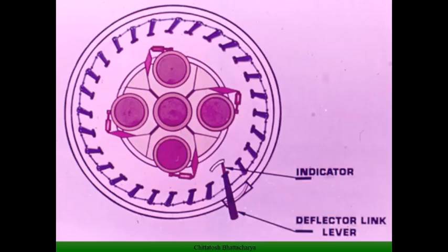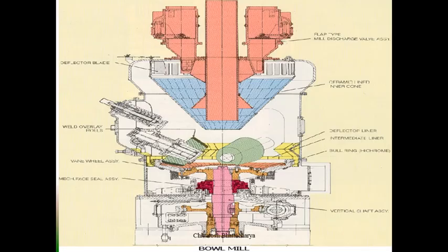Now there are venturi vanes and collars, so that speed can be maintained through the coal carrier pipes, and we also try to have equal velocity distribution across the various elevations, so these venturi orifices are provided.